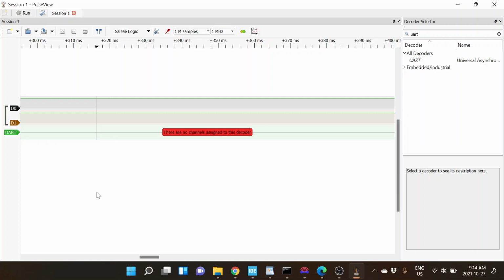When I see this on the lines, I can say, okay, that's transmit, that's receive, or change the pins around to match. Then it'll tell me whether I'm seeing stuff from my ARM chip, or coming back from the Node MCU or what have you. And if everything is right, you should see that transmission going back and forth.